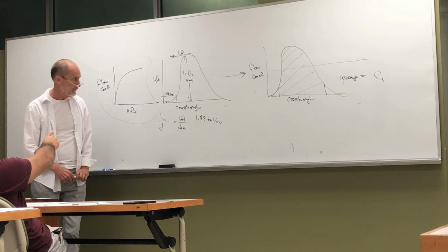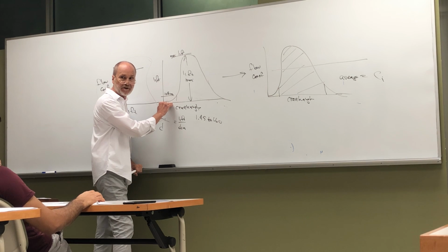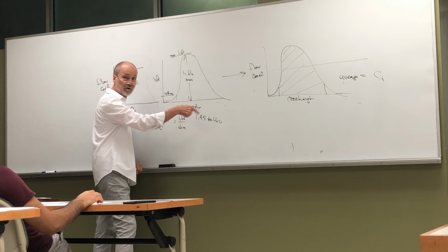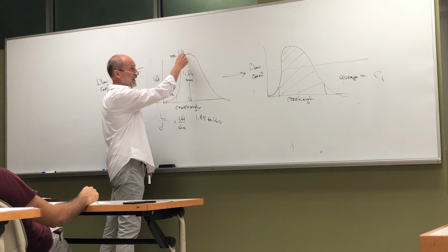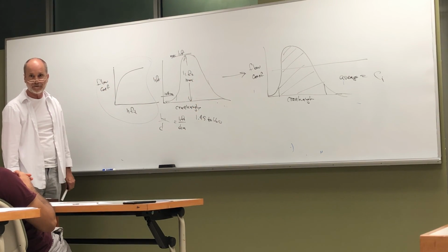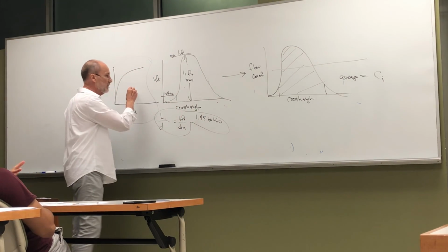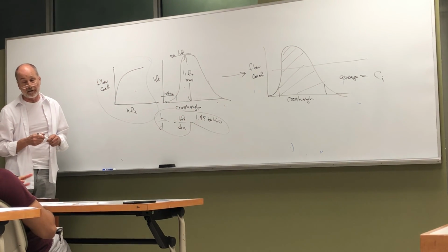What do you lift in this? This is lifting the valve. The valve's on the seat here, and then as the crankshaft rotates, it goes to a maximum lift and back down again. And you divide it by the diameter of the intake? Yes. This is just to get an estimate if you don't experimentally have those two data, which is the only way to do it.